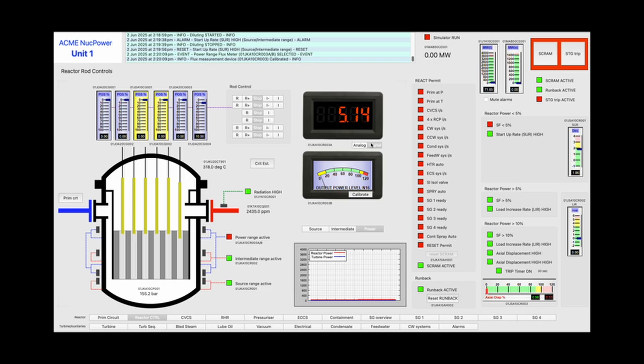Both these power range meters are however prone to wandering from the actual measured value due to distribution of the chain reaction within the core and other factors. They can however be calibrated online, and this should be done on a regular basis to ensure the reading is accurate.